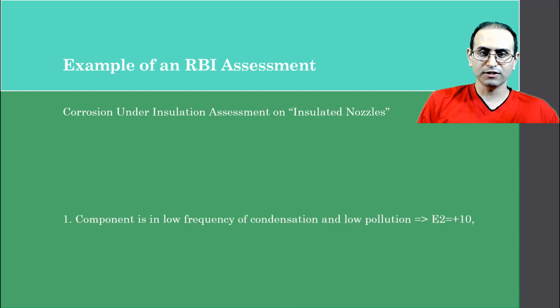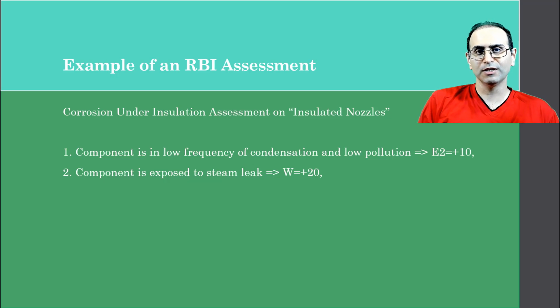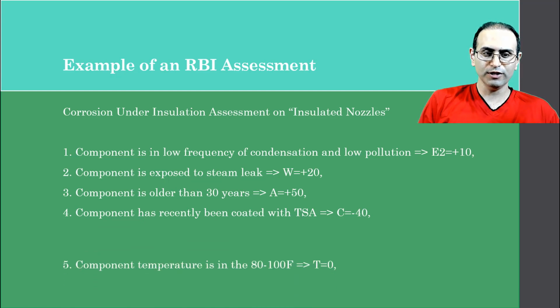So on the insulated nozzles, we know that the component has low frequency of condensation and low pollution, so the environment factor is +10. The component is exposed to a steam leak based on the history review, so the W factor is +20. The component is older than 30 years based on the history, so the A factor is 50. The component has recently been coated with TSA, so the coating factor is -40.